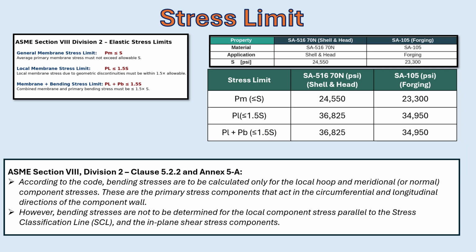It is important to note, according to the code, bending stresses are only calculated for the local hoop and meridional components. Bending stresses are not determined for stress parallel to the SCL or in-plane shear components. This ensures the evaluation is consistent with the code assumption.